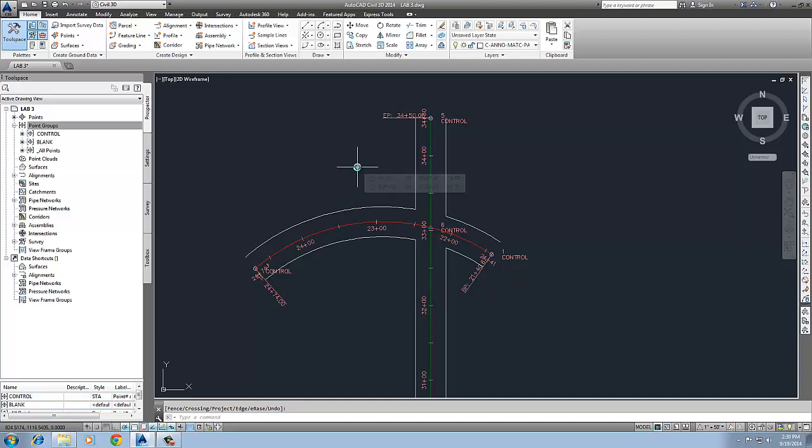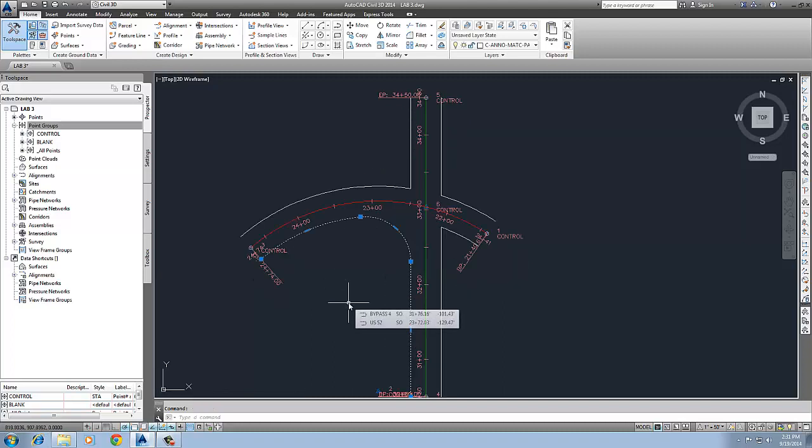So I'm going to go into the fillet command, typing in F, selecting my radius, R, and I'm going to do that southwest first. It's a 60-foot radius. Select the tangent, select the curve, and it brings it in. And that's generated a beautiful compound curve. The other thing it's done, which is really nice, is generated this as one polyline, so it joins them together. And Civil 3D at this point doesn't know anything about this being an alignment, nor does it know that it's a compound curve. So we're going to look at that when I show you the other aspect. We'll see how that works. We're going to go over here and do the same thing.